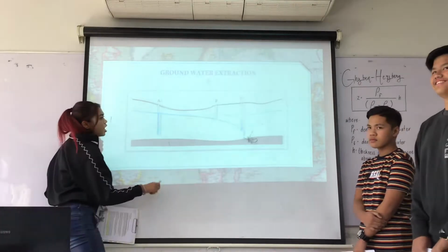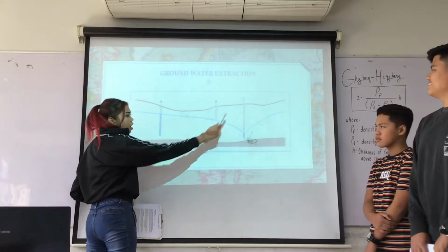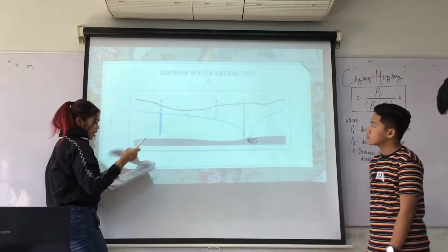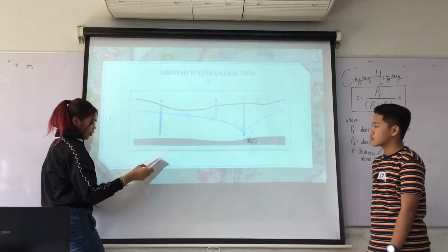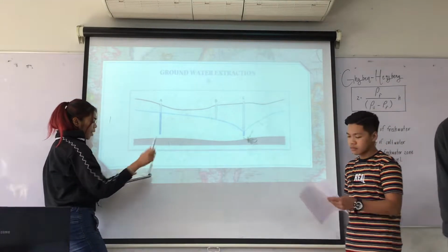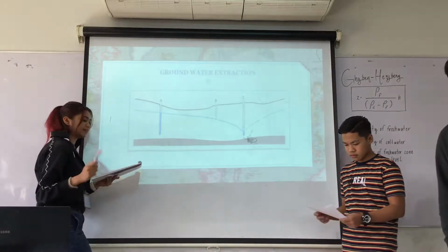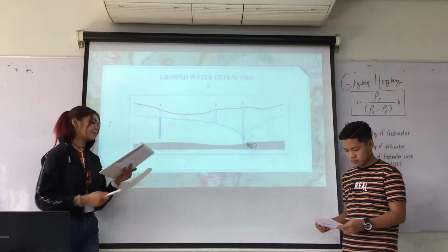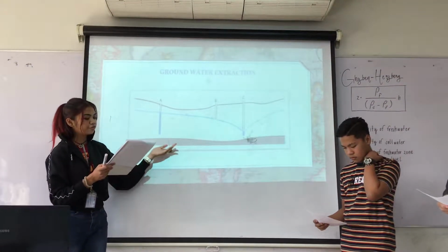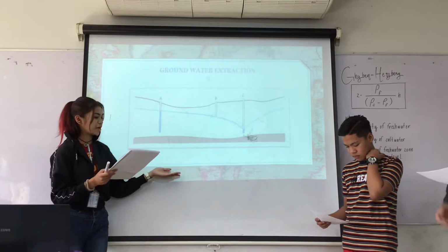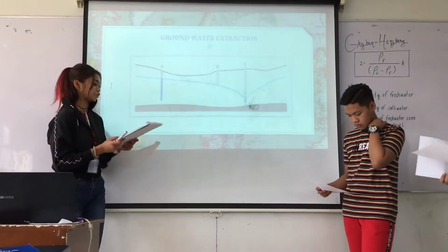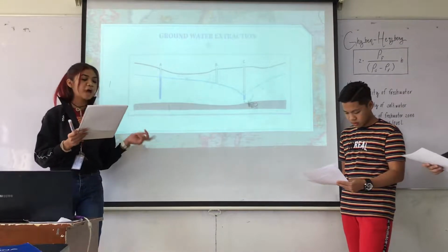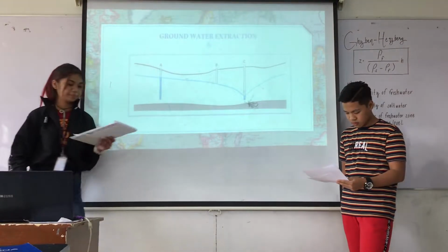Now, for example, if well C is drained too much, then wells B and A will be affected, due to their aquifer or higher groundwater head flowing toward the pumping well, where the groundwater head is now lower. That is how a well gets water from the ground. The water table or potentiometric surface will slope in toward the well where the water is being withdrawn. That indicates the energy gradient that is allowing water to flow toward the well.